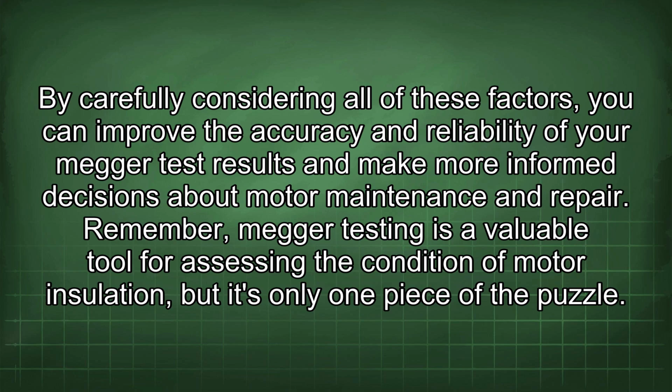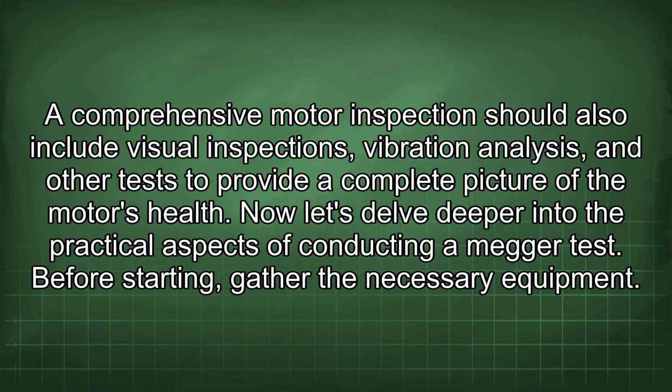By carefully considering all of these factors, you can improve the accuracy and reliability of your Megger test results and make more informed decisions about motor maintenance and repair. Remember, Megger testing is a valuable tool for assessing the condition of motor insulation, but it's only one piece of the puzzle. A comprehensive motor inspection should also include visual inspections, vibration analysis, and other tests to provide a complete picture of the motor's health.